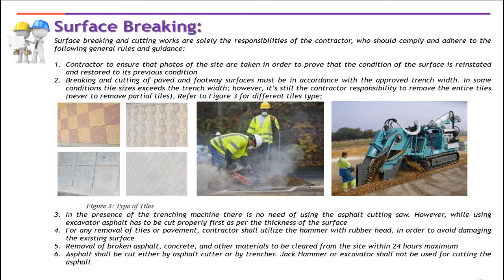If you use a trenching machine, then there is no need to use an asphalt cutting machine, of course. However, if you have a standard trench of 400 mm width and more, an asphalt cutting machine is required. Avoid wide trench and surface breaking as much as possible because it will cost you a lot to restore this pavement if it is beyond STC specification. And of course, those extra materials used cannot be charged to STC.